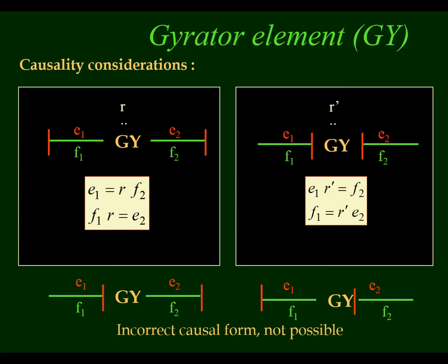And then of course we have the representation of the equations of this gyrator. As you can see on the screen, you can have the two efforts towards the ends, or the two efforts towards the middle, like in this case. This is the case where the flow goes in and gets transformed into an effort. The other one is, when you're studying this GY element and we want to write the equations of motion, you look at what's the output.